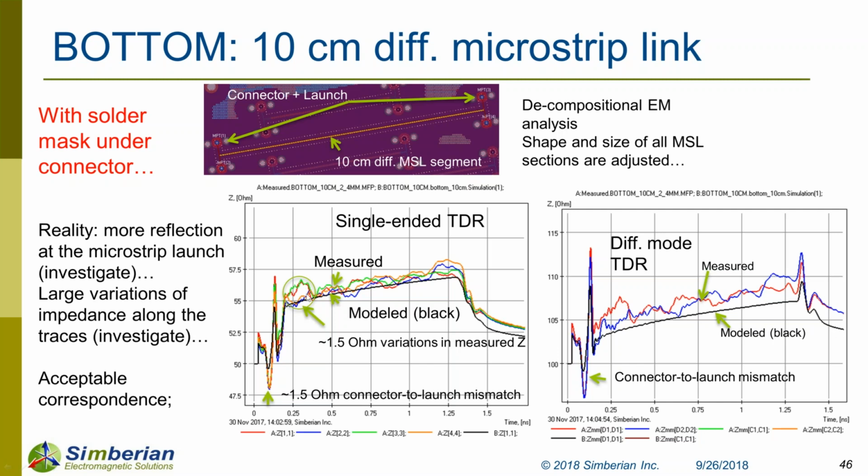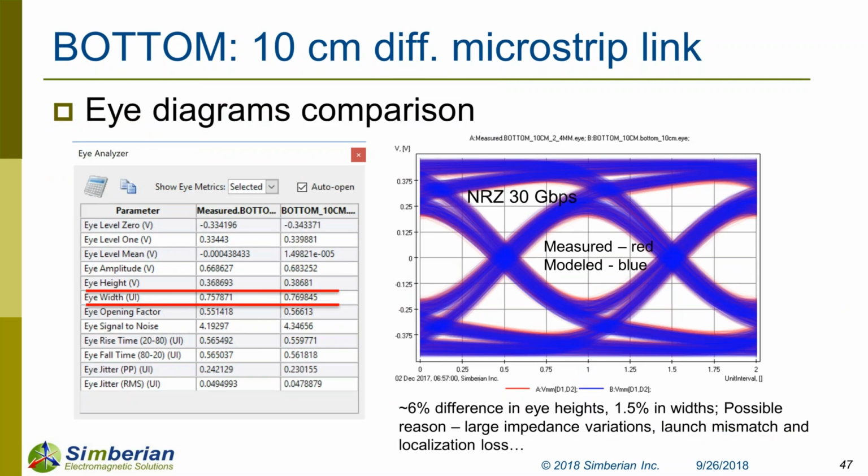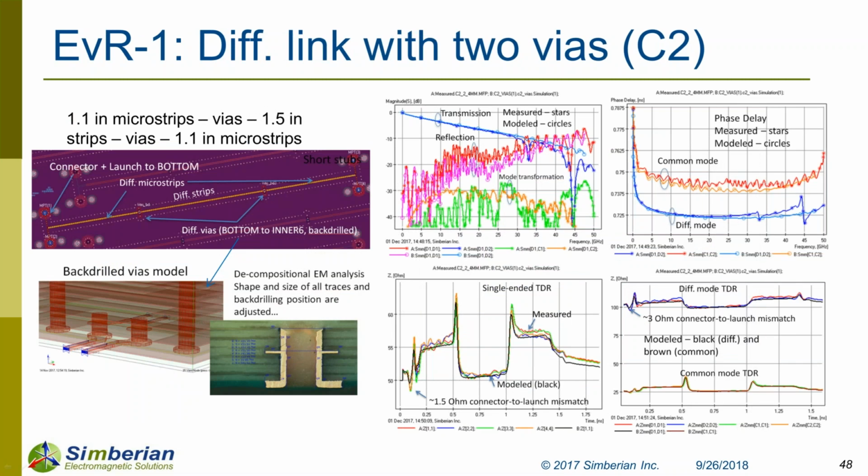When we did a few cross sections of microstrip, they were slightly different, especially the solder mask flow, and that's a combination of different processes: etching first, plating, and then solder mask, which they just pour on the top. This configuration is not really popular for high-end multi-gigabit signaling, and the reason is it's less predictable, and you can see why. We don't really have any statistical data. What causes this is probably a subject for another investigation. But nevertheless, we've got relatively good correlation in the eye diagram for the structure. Again, the eye diagram is computed from scattering parameters, measured and modeled.